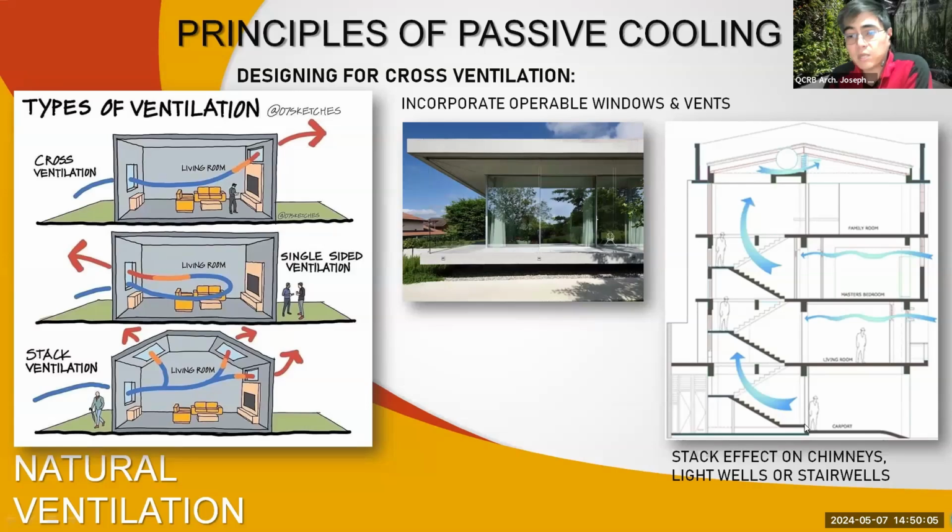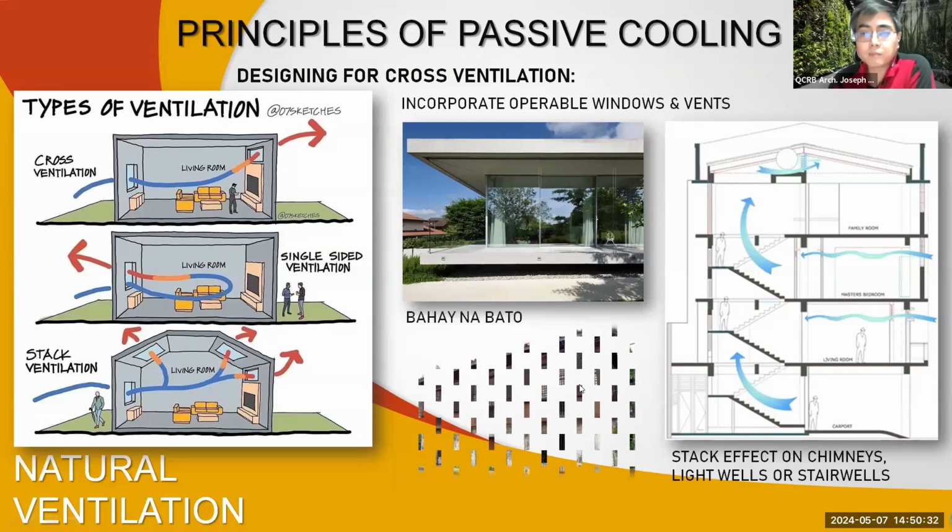Stack effect on chimneys, light wells, or staircases, no. Stack effect ibig sabihin because hot air rises, di ba? So if there's a staircase, normally that's an opening from the ground floor up to the top floor, not dire-diretso. So that means hot air from the ground floor will go to the second floor, hot air from the second floor will go to the third floor and up and so on. And that encourages the air to move from bottom to top. So dun pa lang sa pag-move ng air pataas, there will already be wind movement, no?